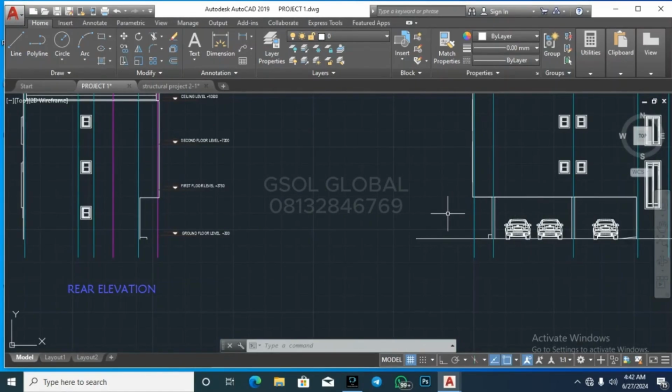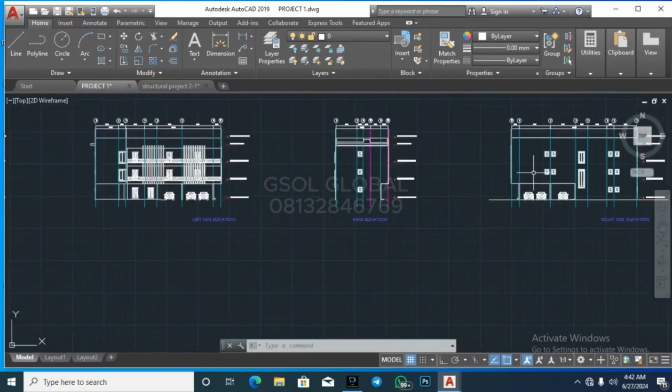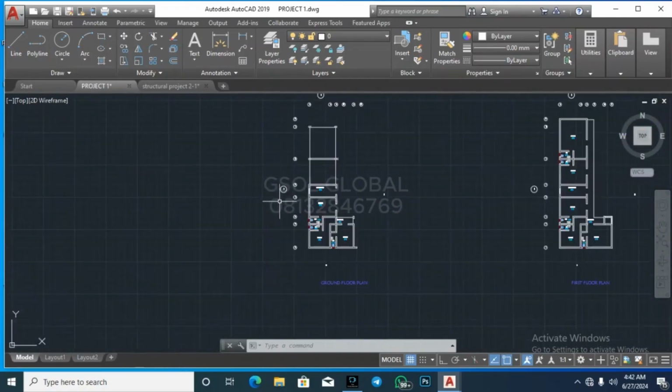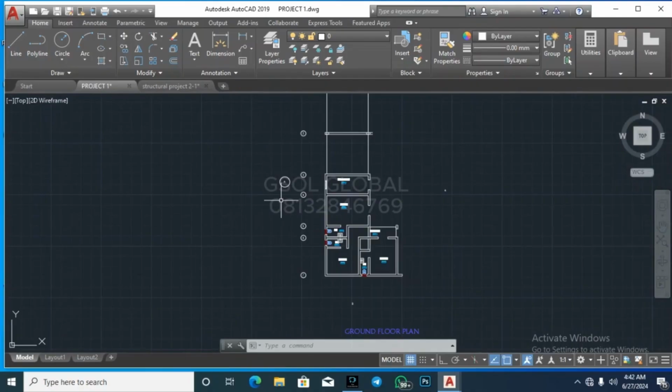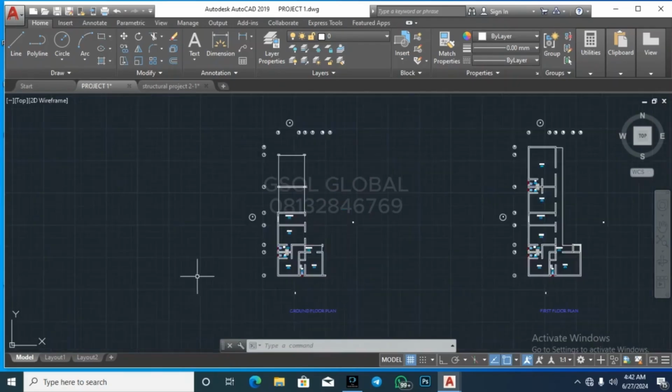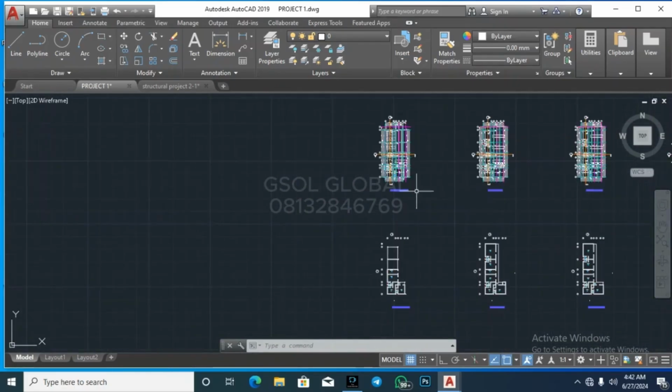But you can see from the elevation that we have cantilevers, but you don't know the side that they are actually. But for me, I'm already seeing the side that they are. But in case you don't understand, we are going to be superimposing so you can get it properly. All right. So now, how do we go about superimposing? Most of the times, the staircase is one of the most common points amidst high-rise buildings. Let's say, okay, this is not actually a high-rise building, but if you have a high-rise building, staircase is mostly sometimes the common point. So what we are going to do here is just to locate staircase area.